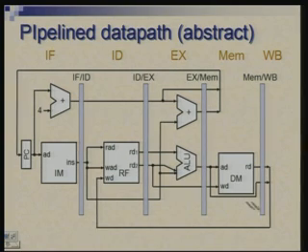a couple of registers. We did introduction of registers in case of multi-cycle design, when we went from single cycle to multi-cycle design. Of course, there our attempt was twofold. We were also trying to share resources within an instruction. We are not trying to do that. By this pipelining mechanism itself, the resources will get shared across instructions. So, we are leaving the single cycle data path as it is and introducing registers.